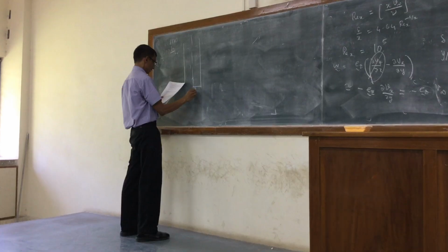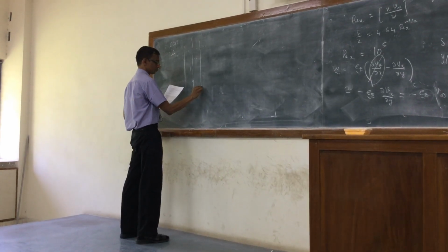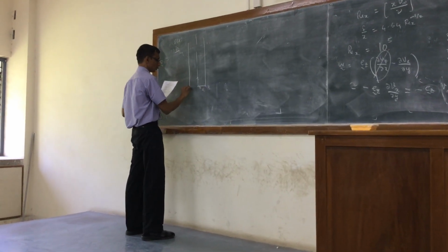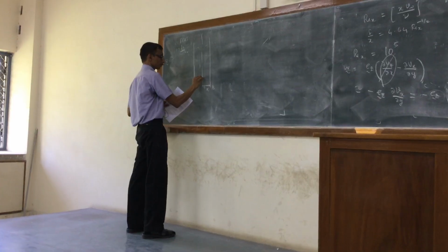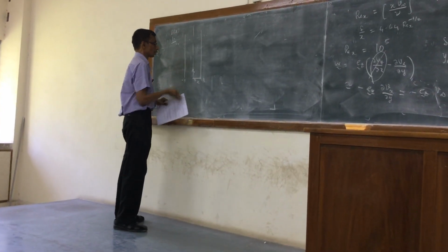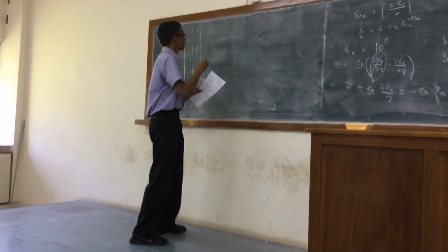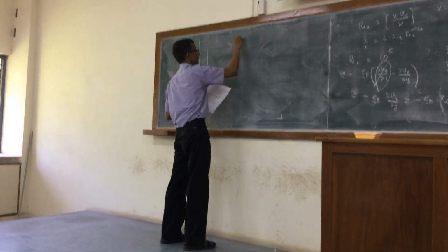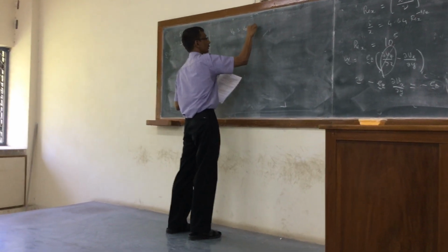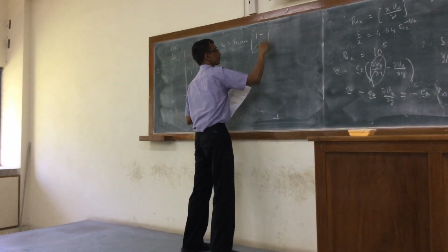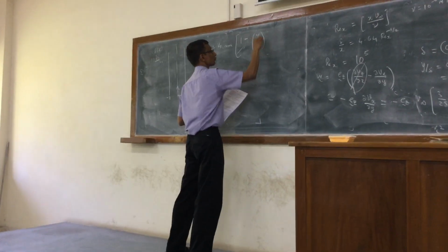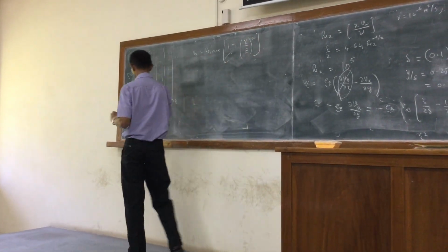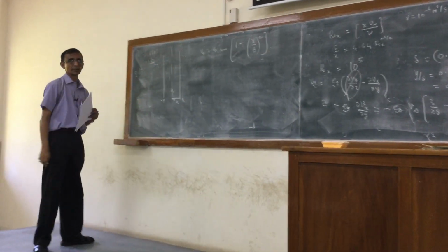This is the x direction, x equal to plus b and minus b. And so the flow, one dimensional flow, you can easily show that vz is vz max times 1 minus x over b squared. It's very similar to the cylinder problem that we had.